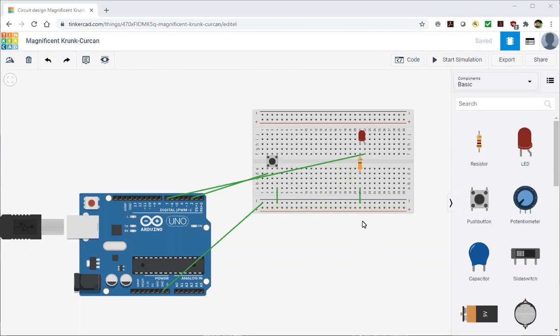But there are instances when the processor might be doing something very time-consuming, and there is no time in the program to monitor or poll that port. As a result, if you push the switch, it's likely that the program is going to miss it, and you're not going to be able to utilize the switch the way you would like.